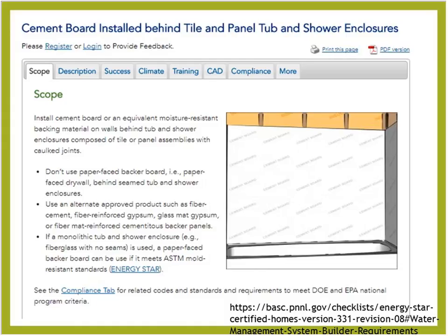And this is something we see all the time when you're building a new home, or even when you're doing a renovation of the bathroom. This is a great time to get into the shower enclosure and put up a non-paper face drywall backer board. And so again, very important to keeping mold and moisture out of the bathroom, along with the proper bath ventilation that we covered in the last session.